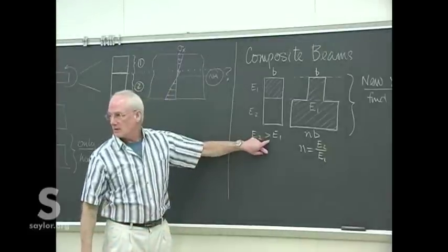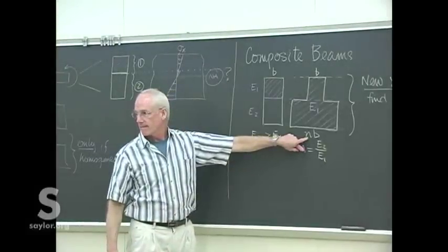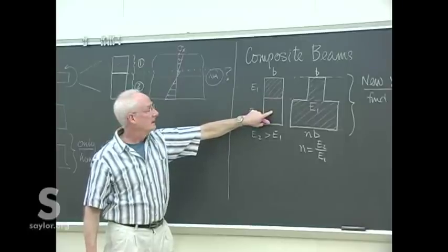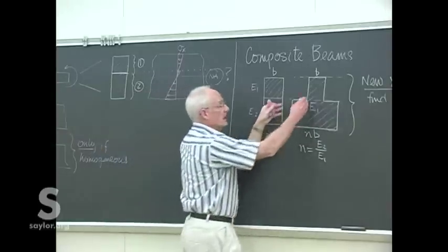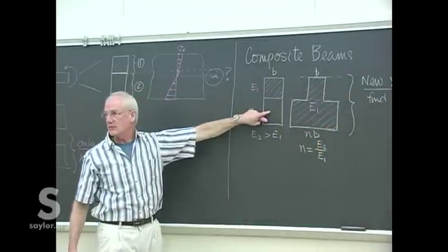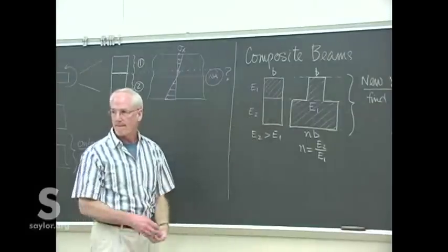And it depends upon what the materials were, because that tells us how wide the new part is. Remember, we've taken out this stiff material here on the bottom so that the entire beam is made of the softer material, so we needed a whole bunch more of that softer material on the bottom to represent the stiffer material for which we're designing now.